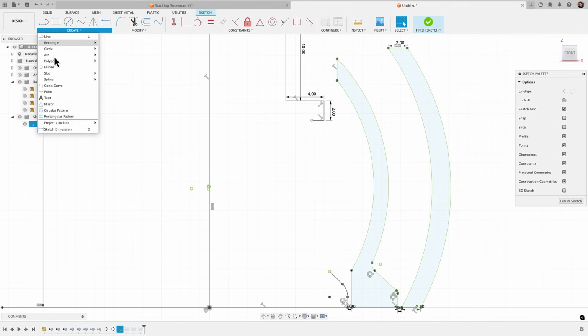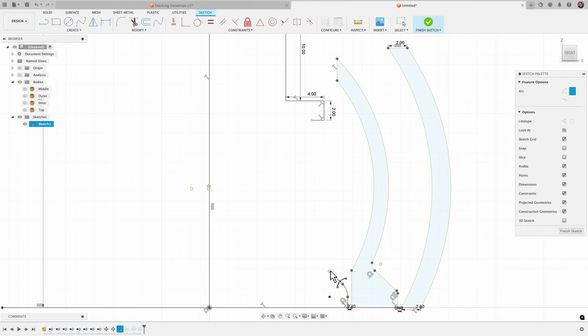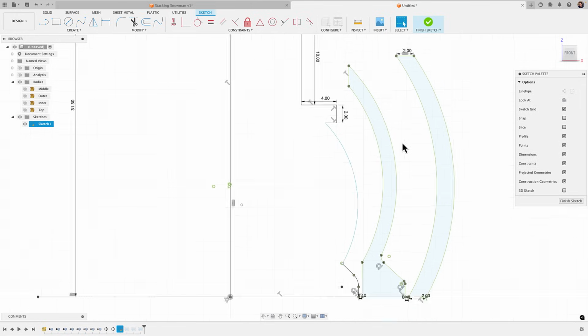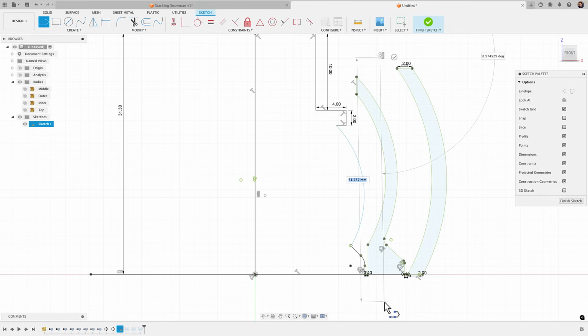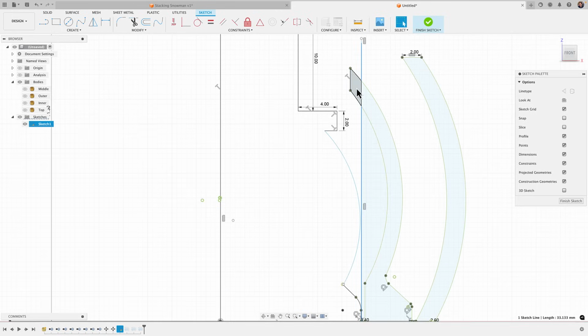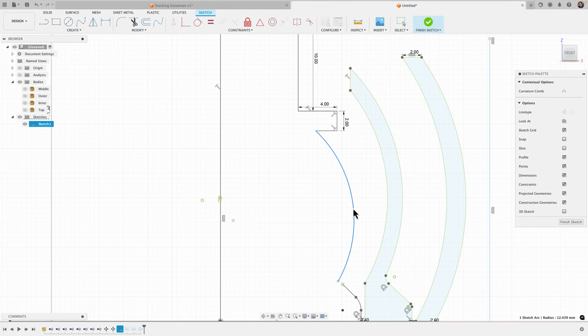Let's see, I'll come in with an arc, and I want this part here to be like the face. But here's where I have to be careful, right? Because I have to make sure, just make a line and make it vertical. If I take this line, no other part of this body can be past this shoulder here, because this shoulder is what has to interfere with that middle section. If the face does, then we're going to have a problem where it's only going to come this far and we won't see the rest of it. So we have to tweak this to bring it in.